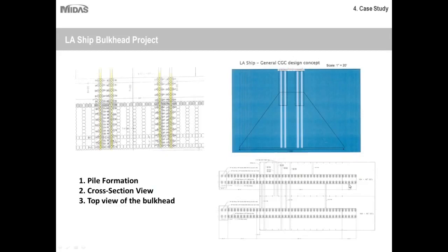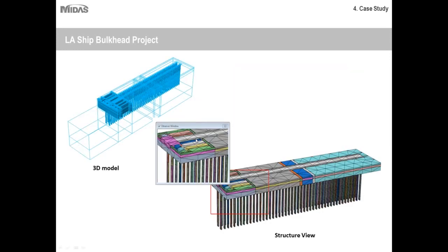As you can see, there were many piles involved with the construction of this particular project, which was sort of a natural choice to use finite element modeling software because of just the scope of this project and the complexity of the analysis that was involved. And the modeling itself was done section by section. So that's another key advantage of numerical modeling programs, is that you can take these large, sort of intricate projects and you can simplify them by breaking them down into smaller pieces.